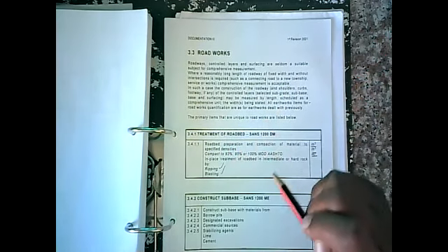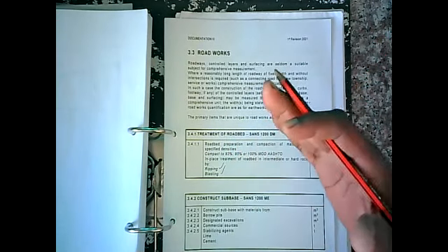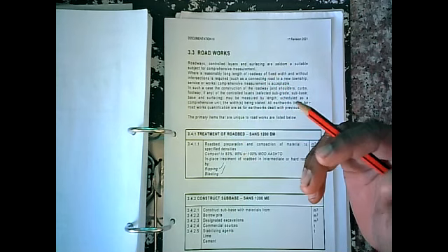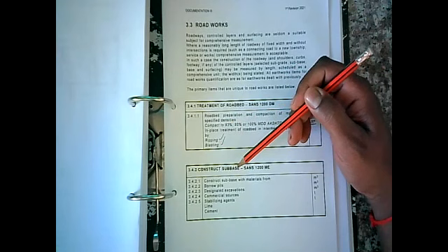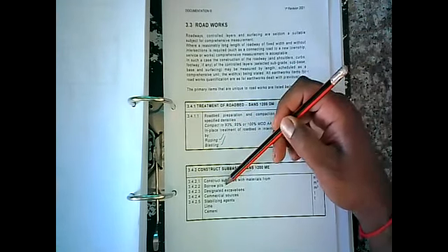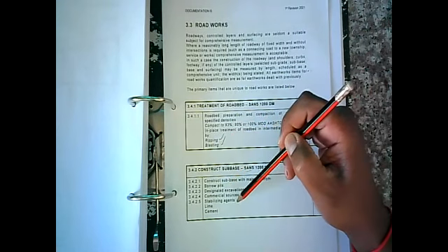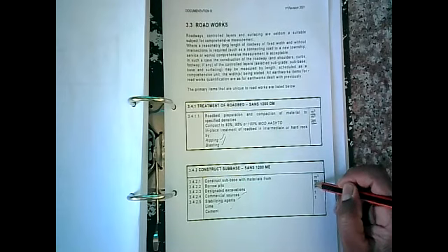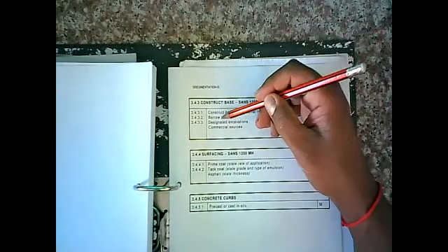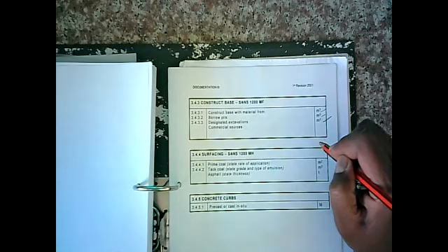All right, so we're going to be experiencing different kinds of soil conditions, and we may have to basically take that into consideration in our calculations. Now, that will make sense as we progress. Construct subbase, once again, still sands. You take it from borrow pits, commercial sources, and we use some stabilizing agents such as lime and cement, all still reduced to cubic meters. All right, base. Construct the base of material from borrow pits, designated excavations, and commercial sources. We'll see that as we progress.